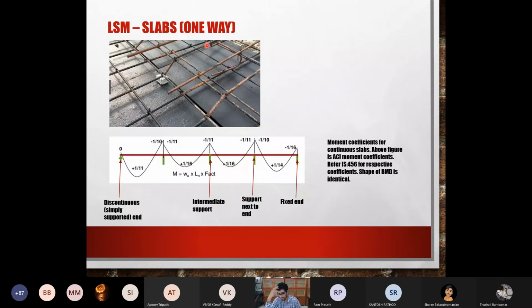Okay, no, that is for beams. You will have to use 0.4% of BD. That's the minimum reinforcement to give in a slab. Okay, point 1. I will come back to that. So there's a minimum reinforcement percentage which you have to maintain in a slab. So you will give that along the other direction.